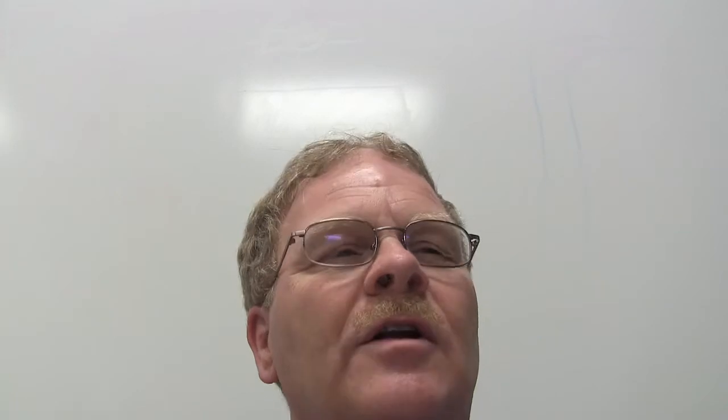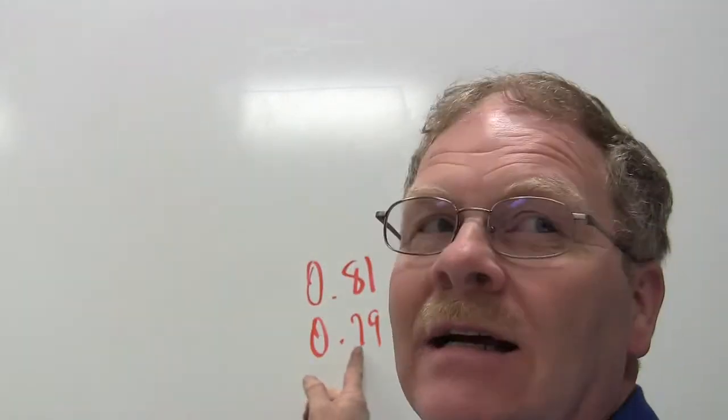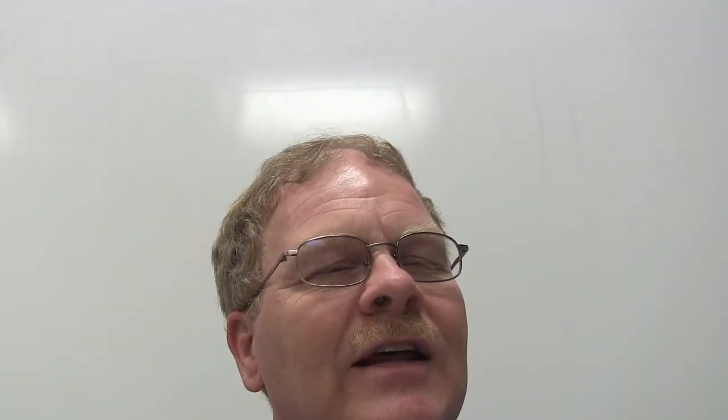All right, now the long and short of it is, I would give this to people for a final exam. You will not pull a trouble code except you might see something that says rich adaptive limit reached. But now you've got to find out. This tiny little imbalance in that mass airflow sensor is enough to cause this thing, at least at idling, to go way off toward Robin Hood's barn.